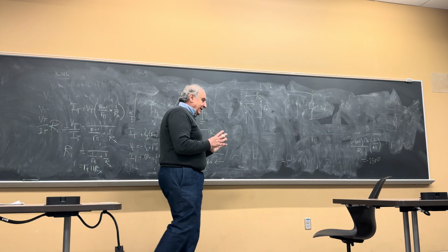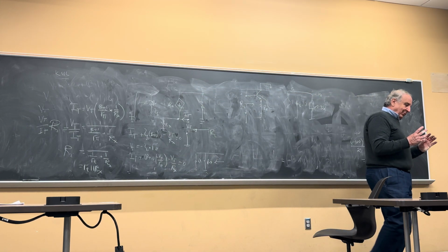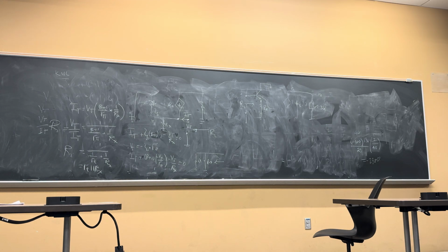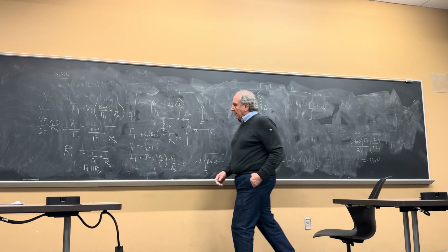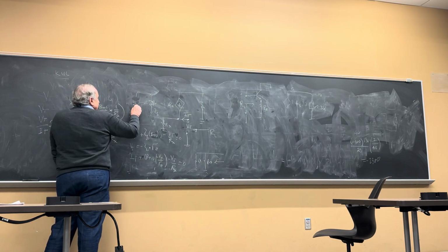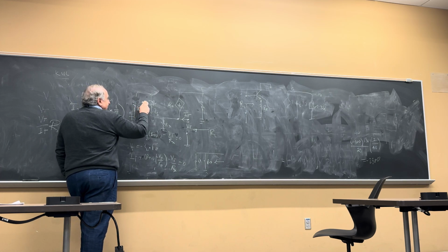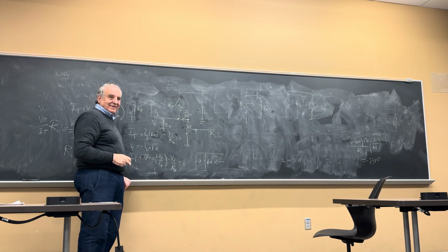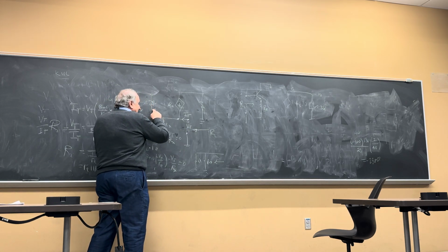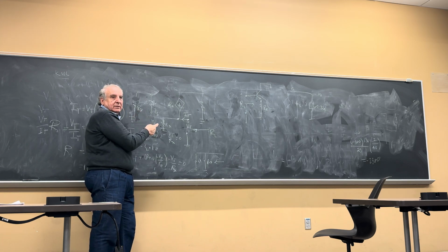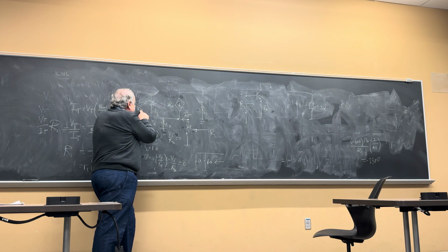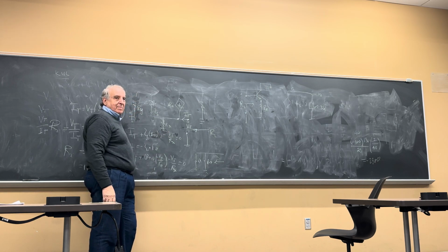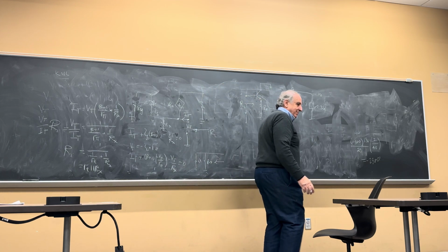So if you're looking up the emitter, you see a little Re. Down the emitter, you see R pi, whatever is in the base, divided by beta plus 1. In other words, if there was something here, say Ry, this will be R pi plus Ry divided by beta plus 1, in parallel with Rx. Looking in here, you got R pi divided by beta plus 1. You add one more impedance, it'll be added to R pi, so it'll be Ry plus R pi divided by beta plus 1 in parallel with Rx. That's the impedance looking through the emitter. It's much lower impedance than looking through the base.